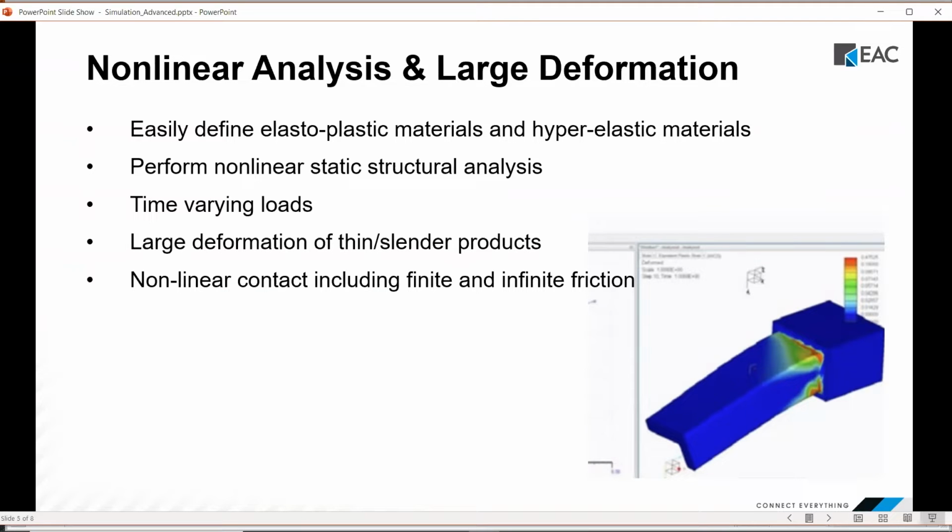For nonlinear analysis, Simulate is still a linear solver, but it can do nonlinear analysis by using a process where all the external loads get applied in steps. The user defines how many steps they want the analysis to go in, and it runs that many times. After each step, the model geometry updates to the deflected state. So for instance, after step 2, it deflects a little bit. Step 3 runs on that deflected state and continues to deflect it even more.